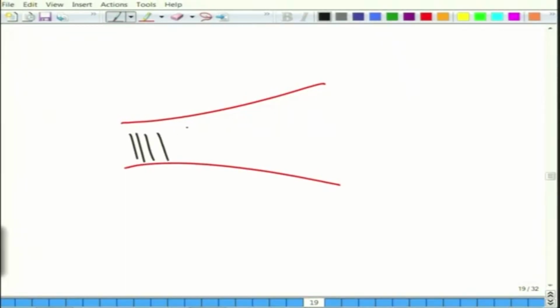We will still assume planar waves, but we will see what the wave propagation equation is for such a duct, and what the transfer matrix is for simple shapes like exponential horns and conical flares, because these systems are used in the inlet portion of the muffler, especially when we go for a special kind of perforated muffler.